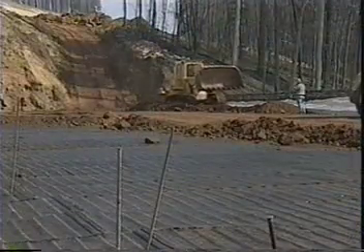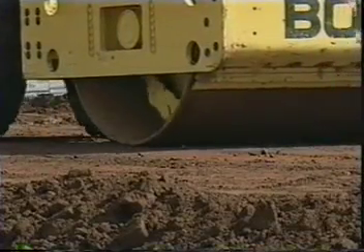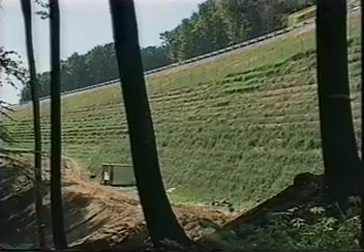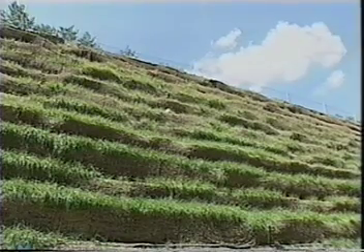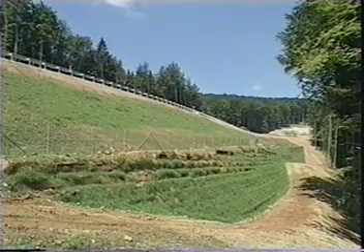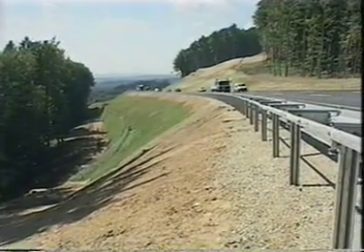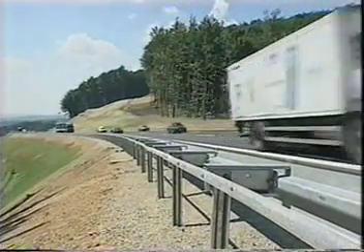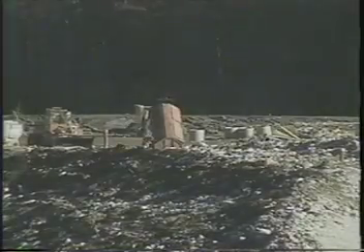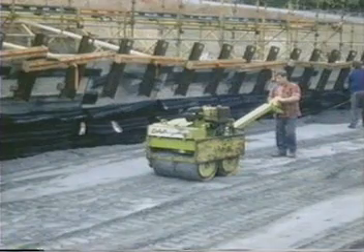During construction, equipment should be kept off the reinforcement, and fill should be placed carefully to avoid damaging it. Once construction is complete, the fill must remain stable over the specified service life. The fill must therefore not suffer significant creep or compaction under its own weight, nor be prone to collapse, swelling, shrinking, or internal erosion if it becomes wet. It is important that any chemical elements in the fill do not cause the reinforcement to degrade beyond design limits.